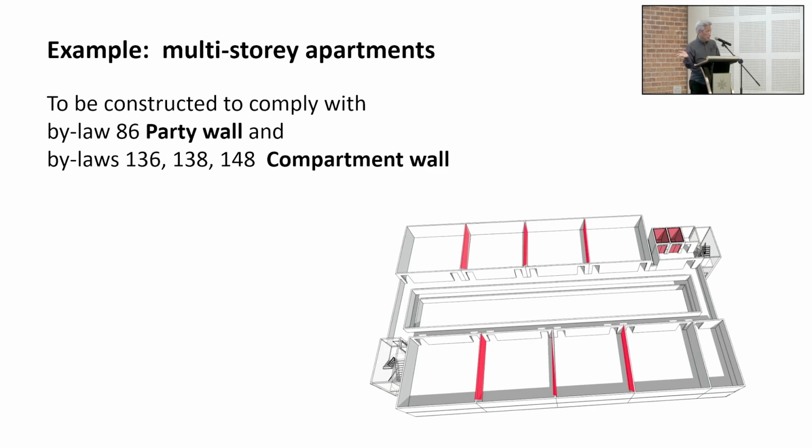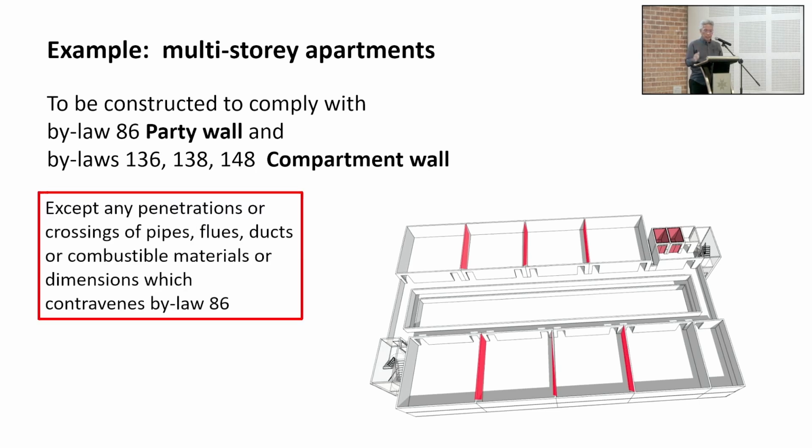Multi-story apartments, again the same thing. These are compartments. They are not separating walls anymore. Why? Because there is that, what clause is it again? The 1.3 something, that every single residential unit in a multi-story development must be compartmented from the adjacent areas. So these are compartment walls. Therefore, it is also a party wall because they are individual units, individual owners, okay?